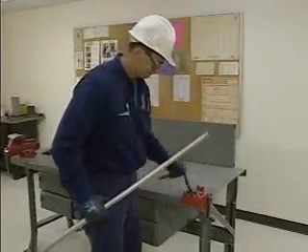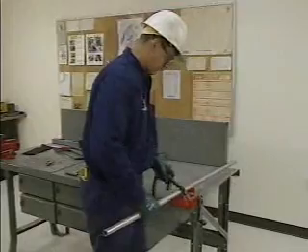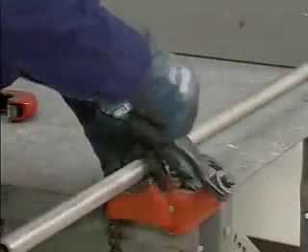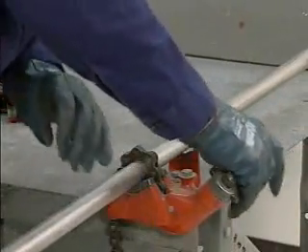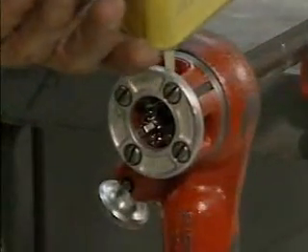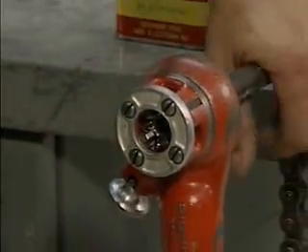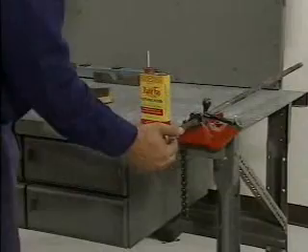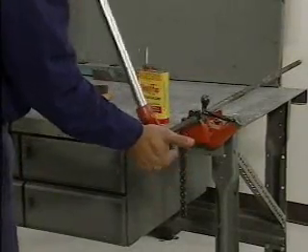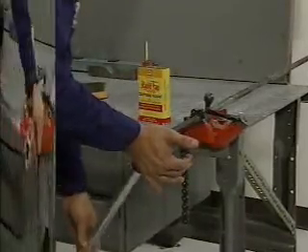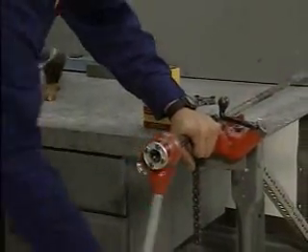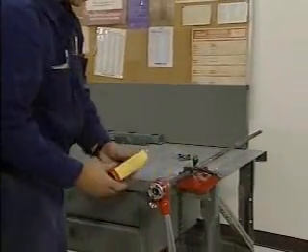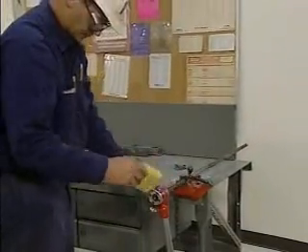Pipes can be threaded in different ways. Electric pipe threading machines may be used, but we'll use a hand-operated pipe die as an example. There are a few basic steps to hand threading a pipe with a pipe die. First, you should secure the pipe in a pipe vise and apply cutting oil to the end of the pipe. This provides lubrication and reduces the heat that's generated when the die cuts into the pipe. Next, press the die against the end of the pipe and turn it clockwise with a ratchet handle. Once the teeth of the die grab the pipe, you can continue turning the die without having to press it against the pipe. It may be necessary to apply additional cutting oil after a few turns as well.